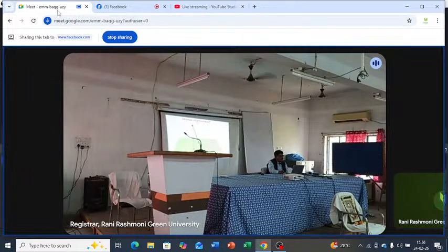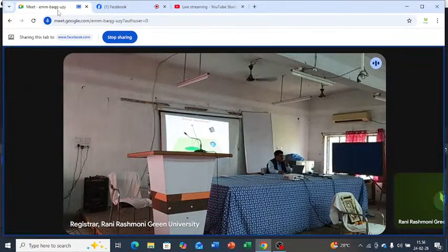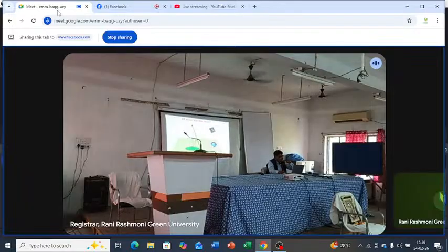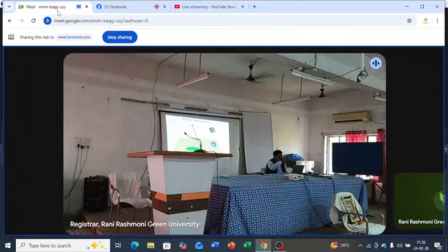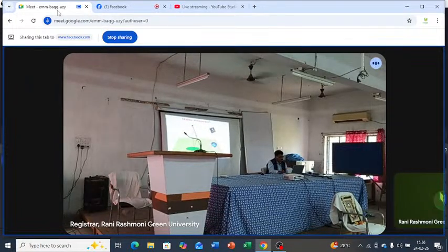So there has to be some calculation or adjustment to be made. How is it done? There is a sensor inside called an IMU, inertial measurement unit, which helps to determine the angle of tilt. And there is a digital compass also built in, which gives you the azimuth angle of the direction of the tilt. Finally, the corrections are applied and you get the position of the pole. This is happening in the background. You don't need to do anything, you just press one button.